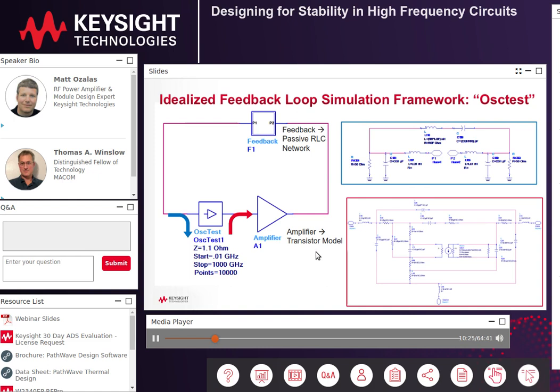Now, both of these blocks are stable on their own, and here's an example then of one way to simulate the loop gain. I'll use a component called OSTest in ADS, which is a special kind of termination, where the forward wave traverses out one side of the component and the returning wave then comes back into the other side of the component. And along those lines, the loop gain is then just S11 of this termination.